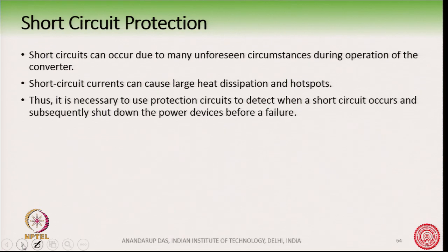So, during short circuit, a large dissipation of heat will happen inside the device and hot spots will develop and eventually the device will burn. So, the gate driver has the important job of withdrawing the pulse and shutting down the power device in a safe fashion before a catastrophic failure occurs.